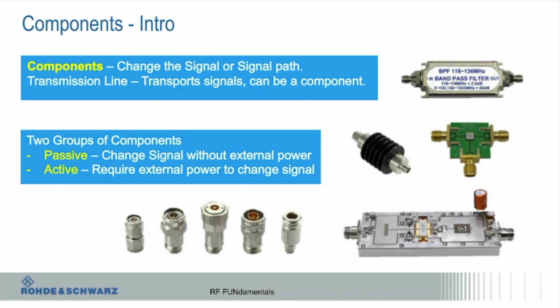You may make some of the similar measurements that you would make on each component, but for the whole system. All said and done, whatever you're making, if you're a component guy, your component goes into a system, and that system has to work, right? So we look over a link budget. What's a transmitter supposed to look like? Can I transmit enough power that can get received at the other end with the right amount of power, and I can decode it and take my information out of it? In the end, that's really what we care about.